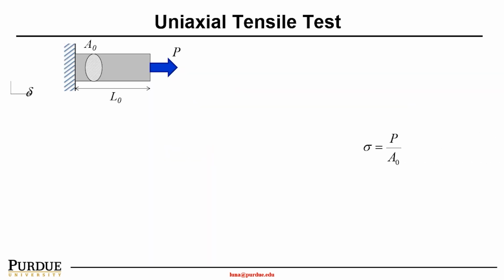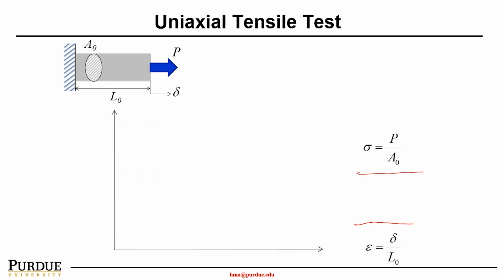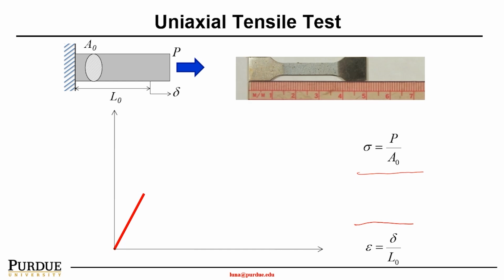Again, let's quickly recap what we learned in this class. We talked about uniaxial tensile stress testing. The tensile stress, sigma, equals the force over the area. The strain, epsilon, equals delta L over L null, the original length. So we discussed the stress-strain curve, which is a very important material property that